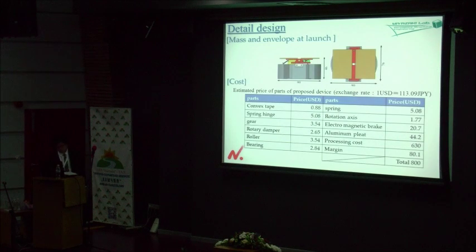Next, mass and envelope at launch. The total mass of the proposed device is 0.246 kg and envelope width 90 mm, depth 76 mm, height 46 mm as shown in this figure. The device can be attached on surface of a CubeSat. So the proposed device fits into CubeSat.